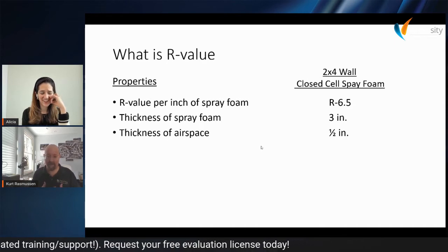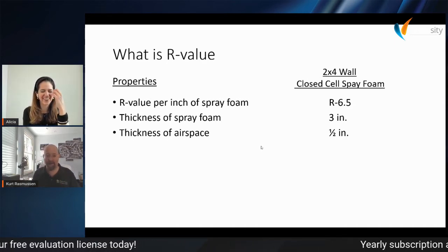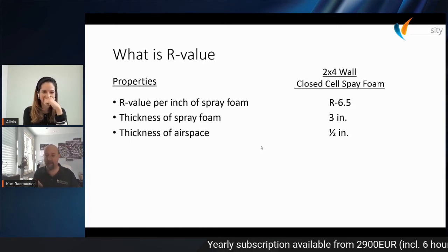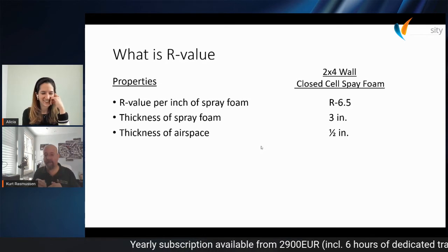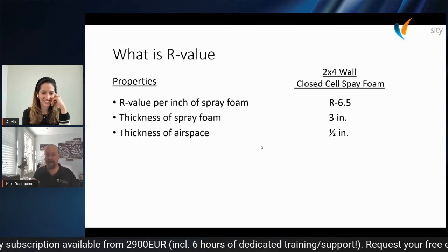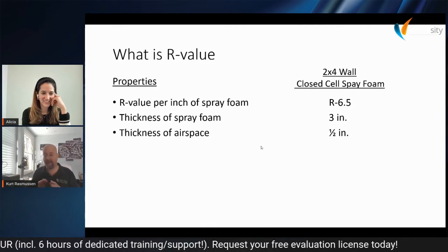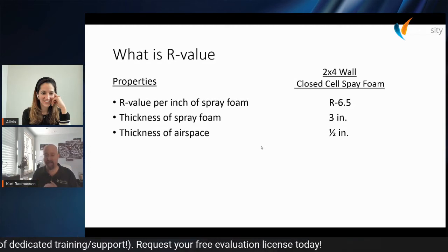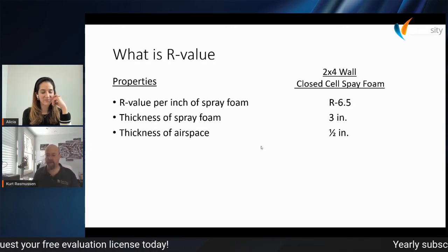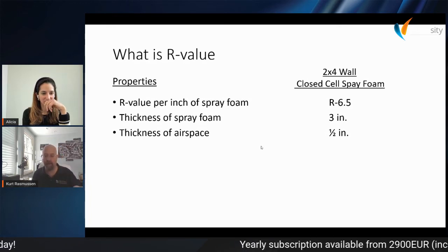Now, I'm all about tolerance. I've done aerial mapping, and I know national mapping standards in the United States is I have to be 90% accurate, or I have to be accurate to half a contour interval on 90% of my project. So when he says 1/2 inch tolerance, I would expect that he has 10% that he would be allowed to be less than that 1/2 inch that we're looking for.